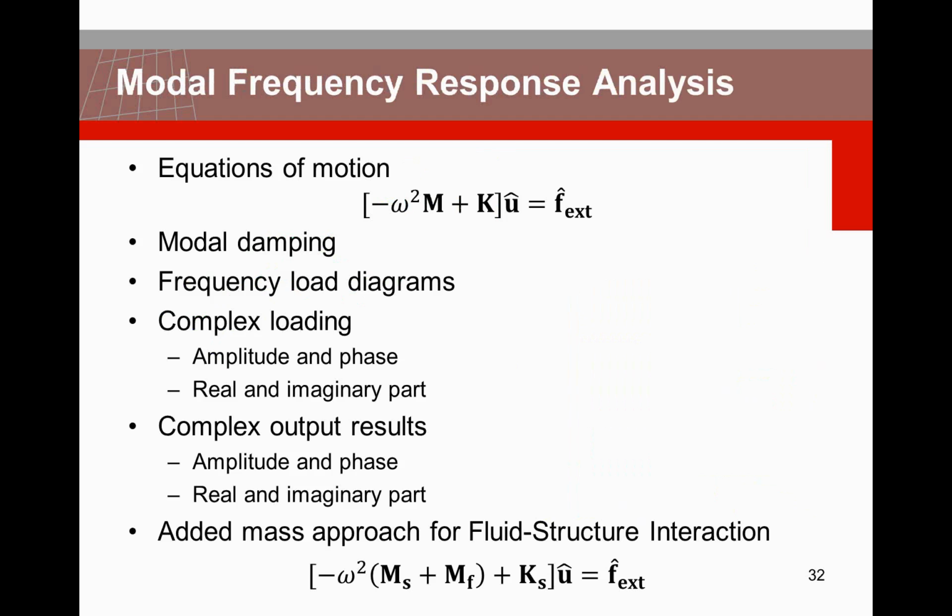In a modal frequency response, we again are using the eigenmodes and eigenfrequencies. The equation of motion is written here again. We are talking now about the frequency domain, so this is a frequency formulation. So we have a complex displacement and we have a complex loading, and there is a relation here between your mass matrix and your stiffness matrix. This looks very familiar indeed as the eigenvalue analysis, and that's exactly what you're using here.